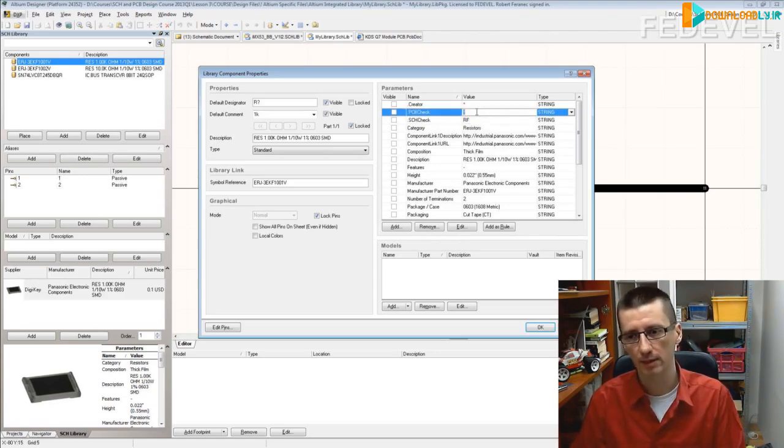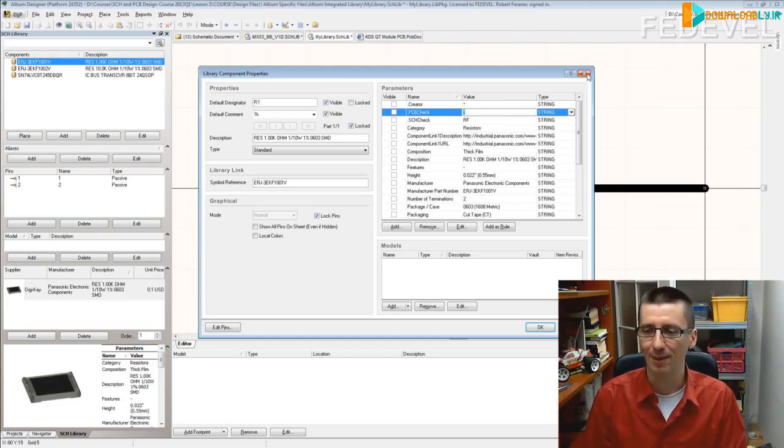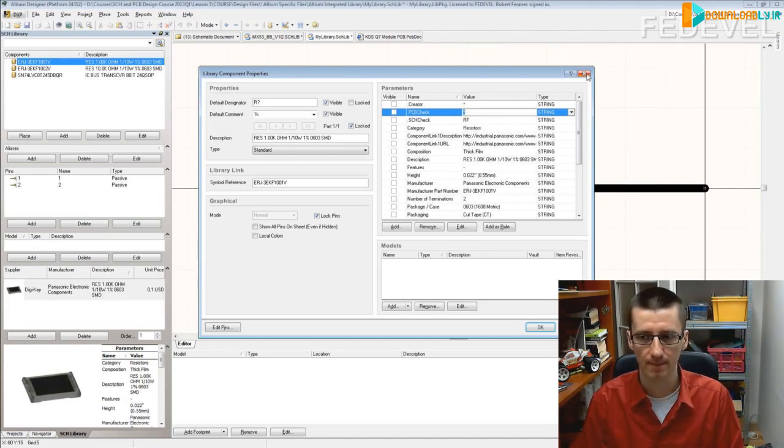When the footprint is checked, put the initials there. Doing it this way, I'm pretty sure the component is safe to use in a design. If there are no initials, I have to check it before the board goes to production. But it's much better to check it much sooner. We will speak about it later, when is the best way to check the schematic.